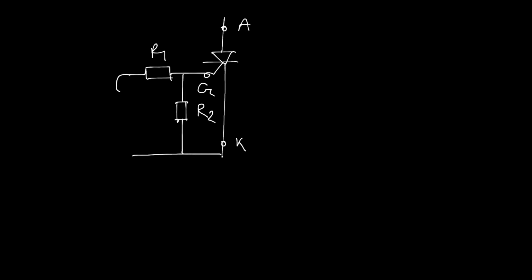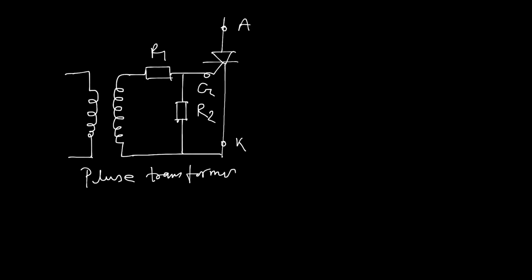And these two terminals are connected to a pulse transformer in this way. This is pulse transformer. Actually, we are using pulse transformer here to isolate the driver circuit from the supply. And normally we use the pulse train or pulse source to trigger the SCR across the gate terminal.